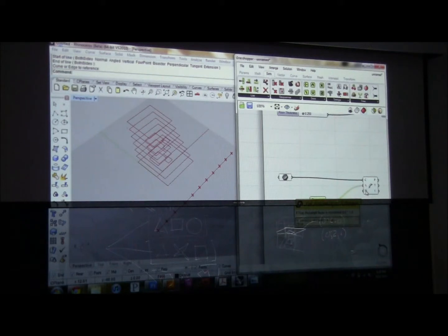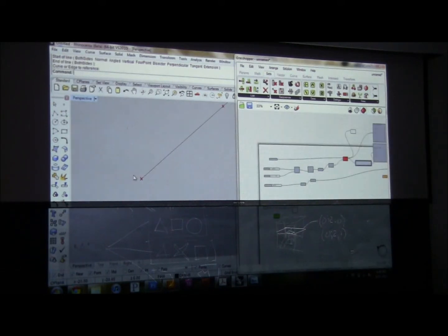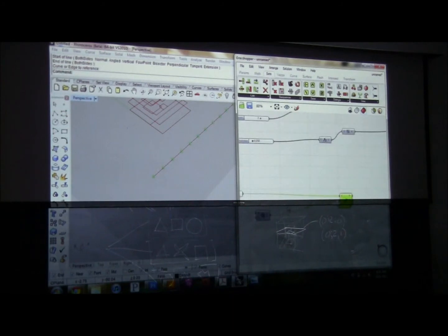Because this is set to true, it's going to evaluate those points essentially as a percentage of the total length. If this were set to false, those would be real units, right? So instead of 10% of the length, it's 0.1 units, 0.2, 0.3, and so forth. So what I actually like to use this in conjunction with is the graph mapper.